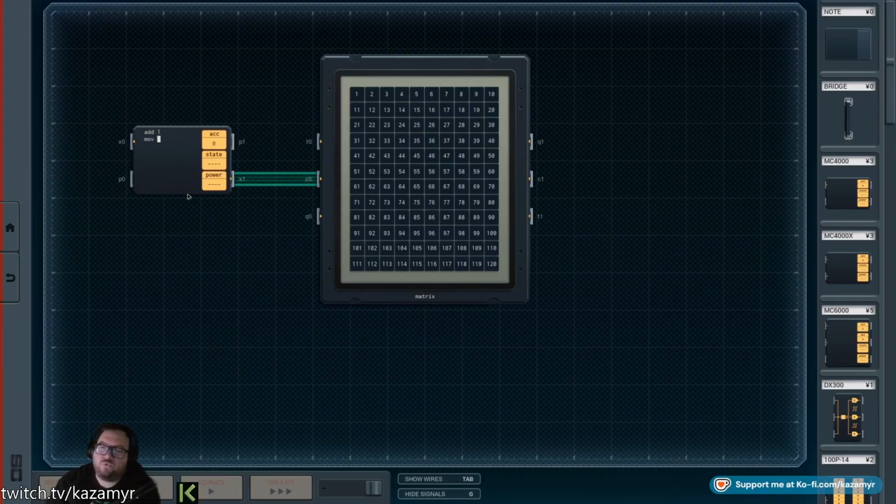We'll move accumulator to x1, and then we'll test equal the accumulator. If it's 120, which is the last segment that we've got, we're going to move negative 121 into the accumulator. And that'll basically reverse it.